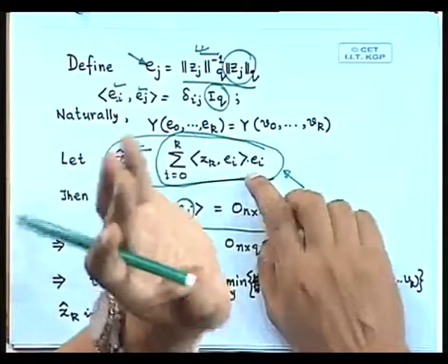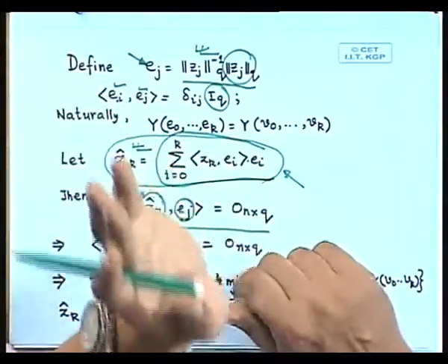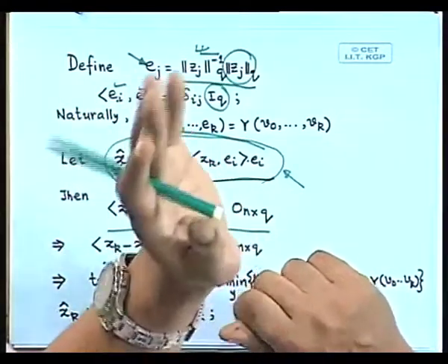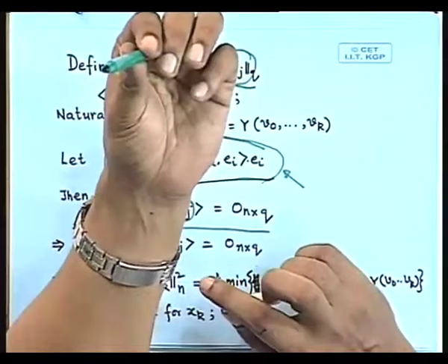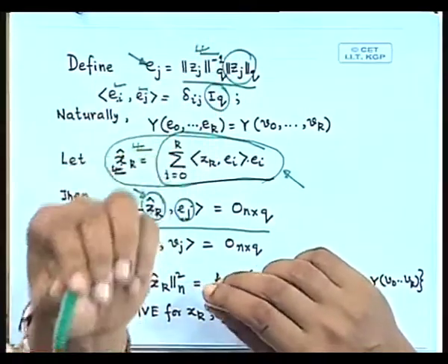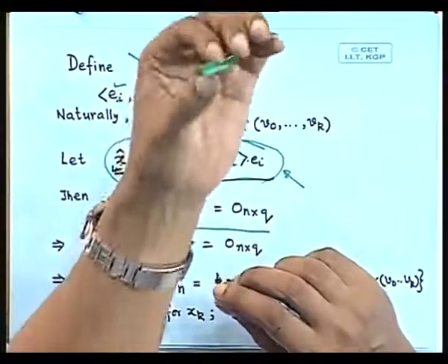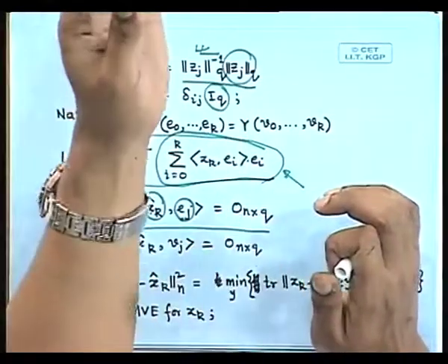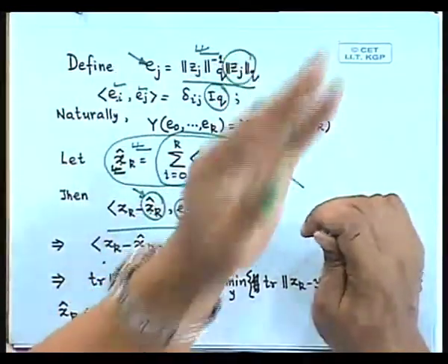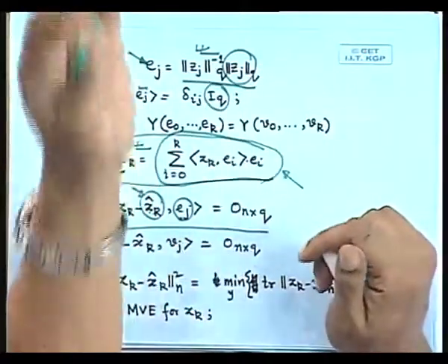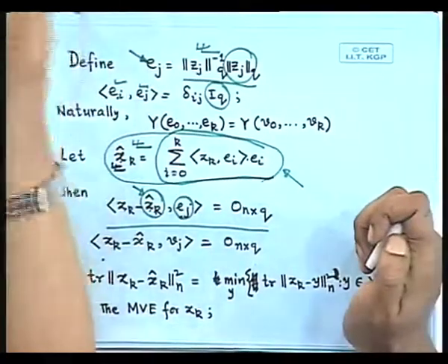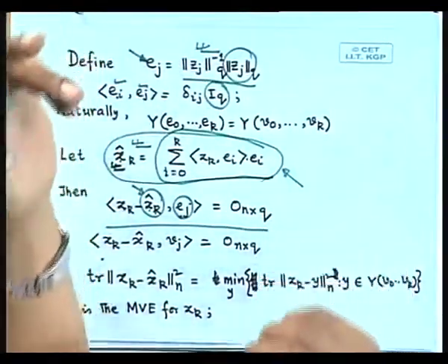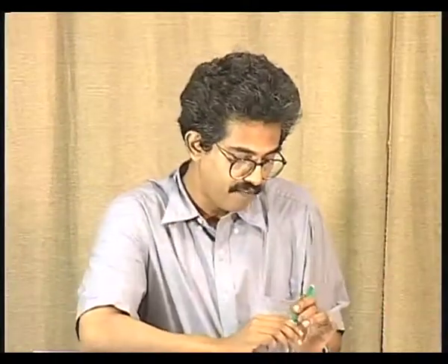We are not going to do the derivation, but all we wanted to say is that this is another approach of deriving the Kalman filter which uses the whiteness of the innovations property. In that approach we want to construct a filter such that the innovations become white, and it turns out that if we can do so, then we arrive at a minimum variance estimator, which is the Kalman filter. That's an alternative way of deriving it. Okay, so I am skipping all the painful other details.